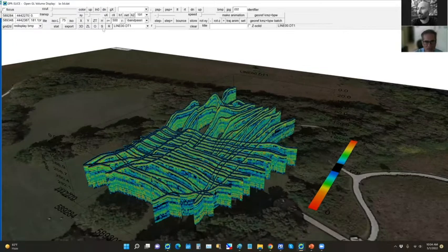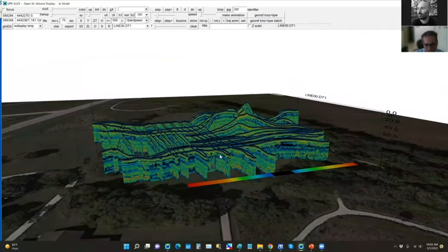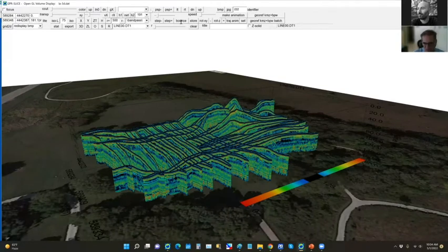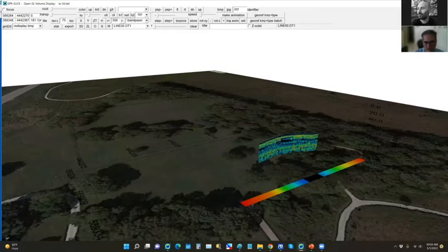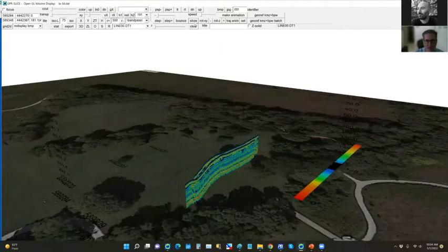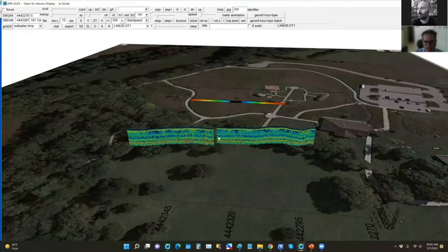We do have this option here in GPR Slice where if you have a large profile and you want to look behind the profile or data inside here, you can actually choose a scan length. Let's say I chose a scan length of 500. You can hit R+, and then hit this bounce button, and you can actually see how the data was recorded on the site. And you can actually change the length of this to whatever is a convenient length so that you could see past it. And you can actually hit the button called Store and see this continuing on, and you can rotate it around. And if you wanted to store that one part, you could store that part. I just hit the Store button again. And then so you could look at the different parts of the data more conveniently.